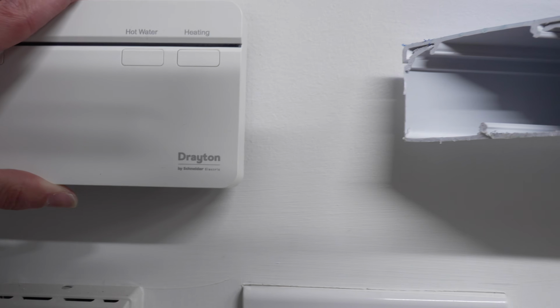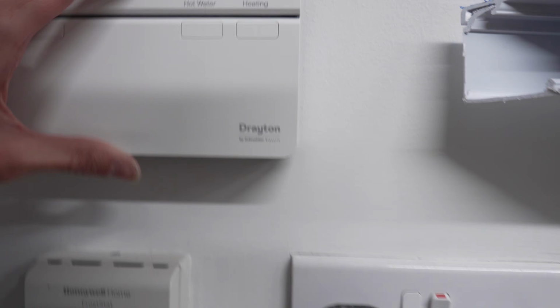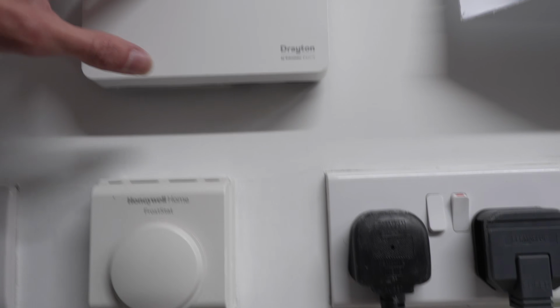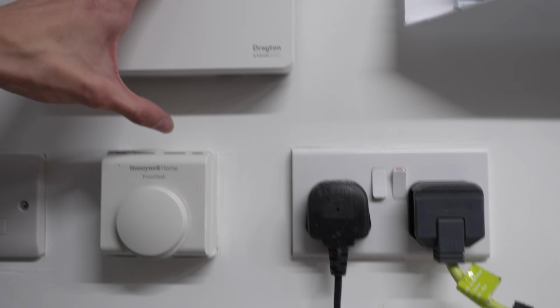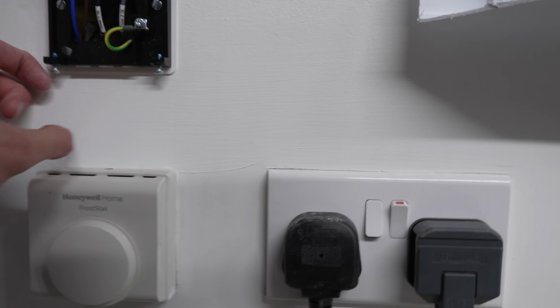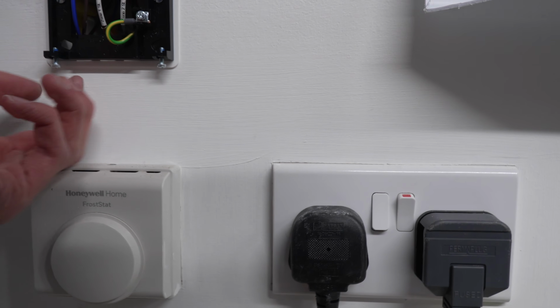To install the hub, you just loosen the two screws on the bottom off, and the hub will just plug on over like that, and you just need to tighten those two little screws up. Now, you do need to watch for situations like this where you're installing the hub above something else. This here is absolutely fine because there's enough of a gap, you can get a very small screwdriver, like the bit out of a screwdriver in there, and tighten that up.